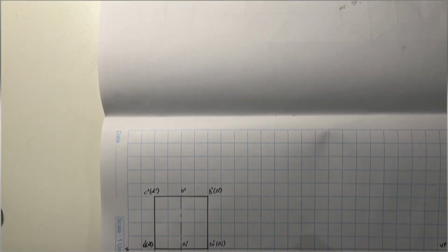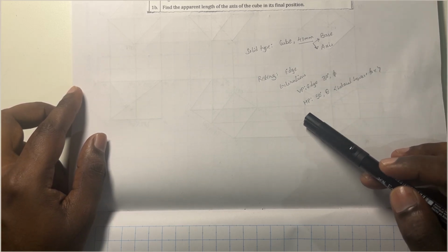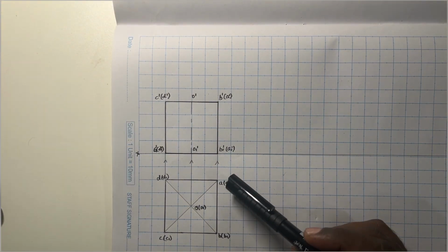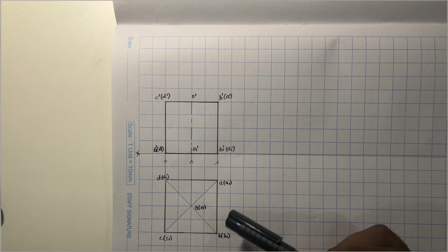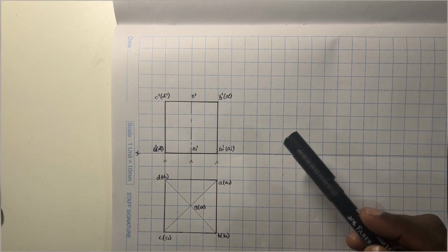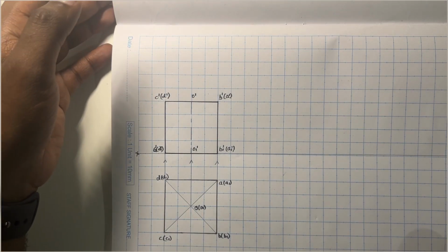For the second position, we need to take the clue from the inclinations that are given to us. In the second position, the lateral square face containing the edge on which it is resting is inclined to the horizontal plane at an angle of 50 degrees. So it is resting on one of its edges, A1 B1. The lateral square face is the one which is going to emerge from that edge, and that face is A1 A B B1. So that face is making an inclination with respect to the horizontal plane at an angle of 50 degrees. Now let us proceed to understand how this 50 degrees can be constructed.